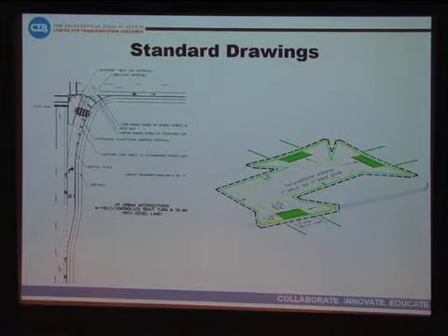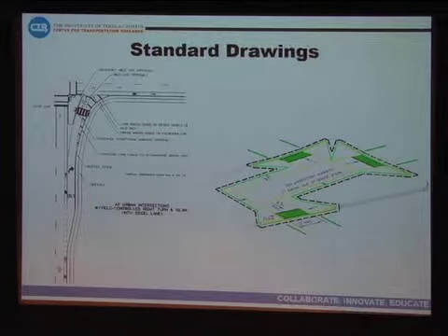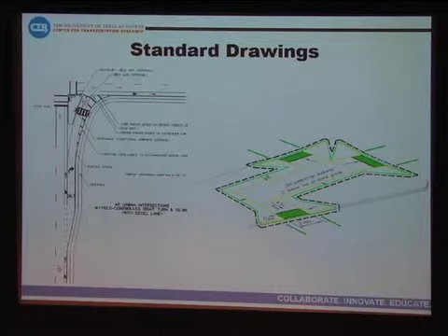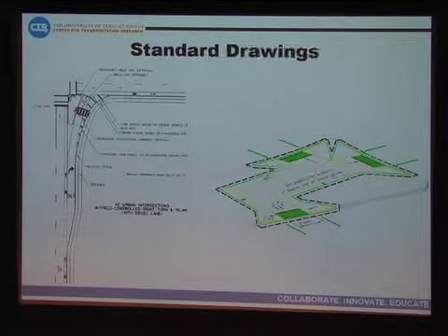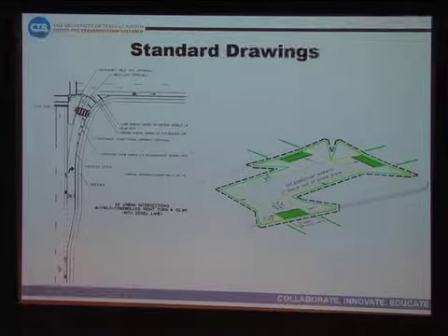Supplemental to those drawings, we have sort of a layout for the pedestrian pathway through the channelizing island. We were looking at some of the benefits of either the cut-through concept or the raised walkway. So the research shows that the cut-through pathway is recommended for pedestrians with disabilities. It helps them with wayfinding and getting through those islands. The concern is, though, that they can collect debris or water, and that is something that we want to avoid.